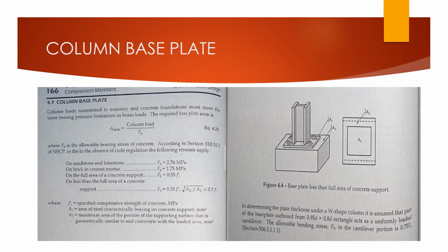So for support we have a bearing stress of 0.35 f'c times square root of area 2 over area 1, which should be less than 0.7 f'c, as you can see. Here is the illustration of the base plates.